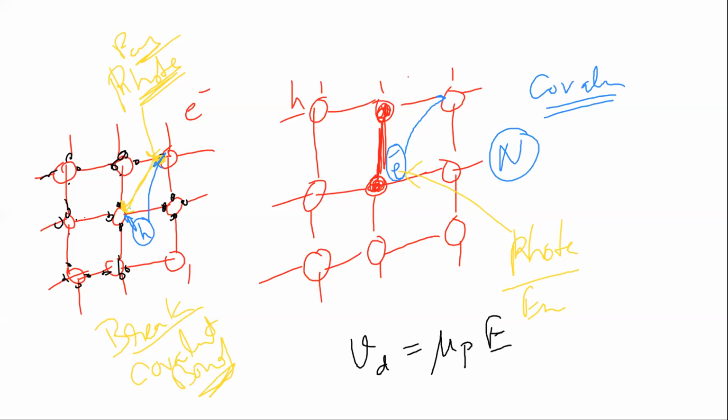In holes, basically the holes are traveling, but there also electrons are flowing, and those electrons are part of a covalent bond. So you need more energy to transfer electrons which are part of a covalent bond, and less energy to transfer an electron which is not part of a covalent bond. That means with respect to the type of material, the mobility is going to change, because of this relationship we are talking about.